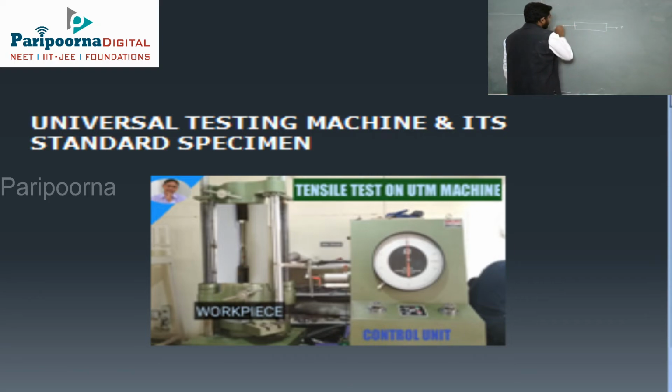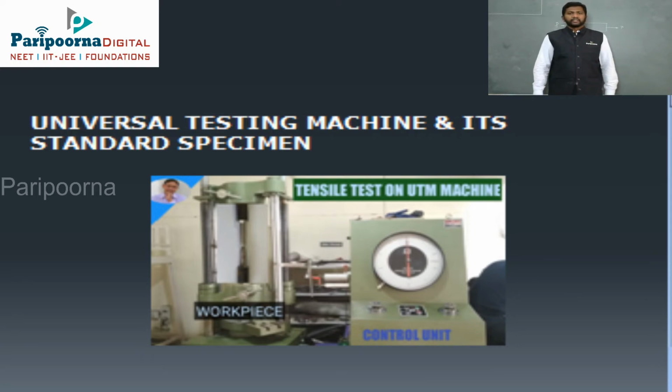So the specimen is placed between the fixed jaw and the movable jaw, and the movable jaw moves along with the specimen. When the movable jaw moves, it means load is applied, so the length will increase. The load is applied from the value 0 to maximum.